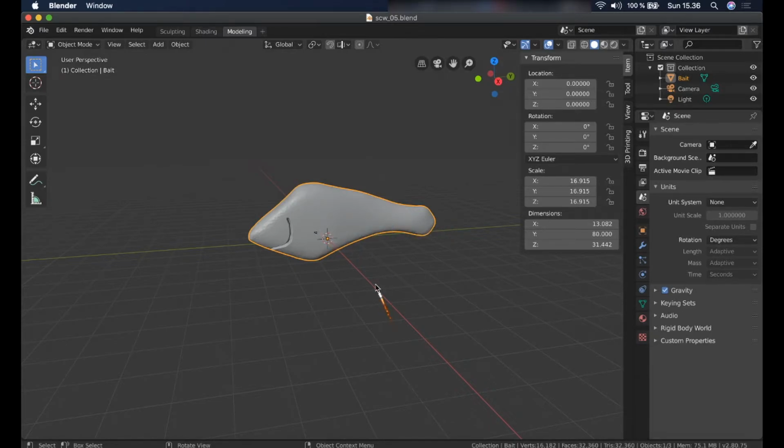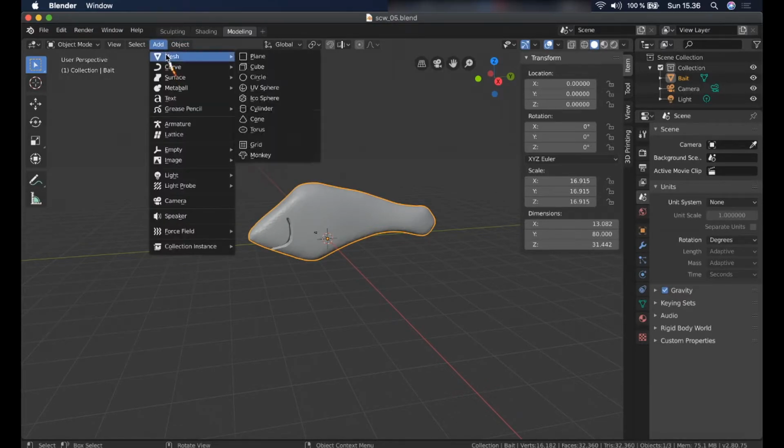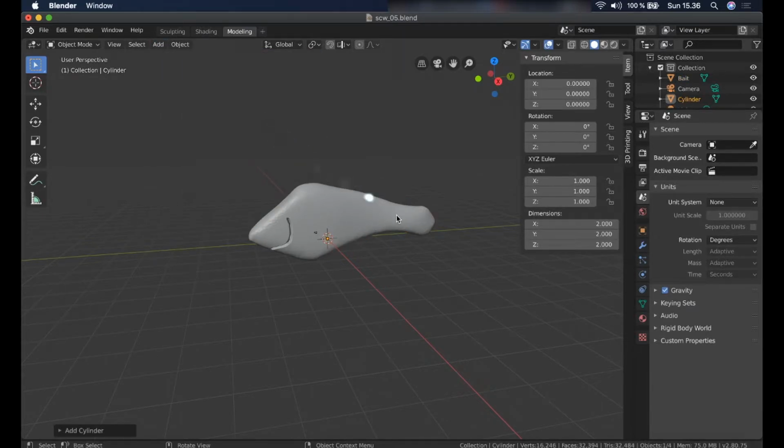For that I will add new objects. So I will add the mesh cylinder and the dimensions, let's see, so on Z it can be whatever, so I will use 70, and I want a bit thicker, so maybe 3.5 millimeters hole, or let it be 3, okay, 3 millimeters hole.